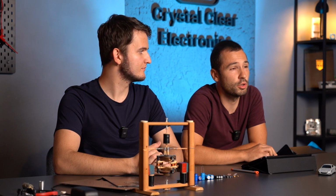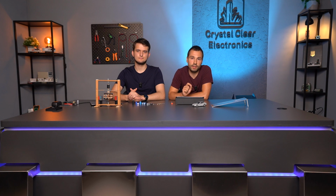Continuous electrical current can be generated by a circuit whose main parts are the battery, the conductor, and the consumer. At the negative terminal of the battery, there is an electron excess. At the positive terminal, there is a lack of electrons because of the chemical processes taking place there. When connected to the consumer with wires, the electrons from the negative terminal flow through the conductor and the consumer, reaching the positive terminal of the battery, trying to equalize the charge difference. The battery replaces the electrons at the negative terminal with the chemical processes taking place in it.